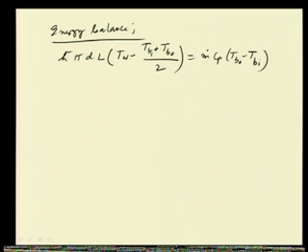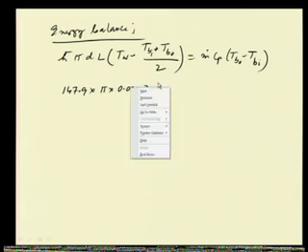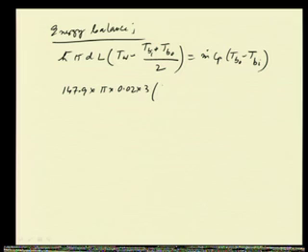So, this is that sensible heat that is being taken away by the fluid. m dot is the mass flow rate of the fluid. If we put these values here, we get 147.9 into pi into 0.02 into L, which is 3 meter, into (80 minus (50 plus T_bO)/2). T_bO is of importance to us, it is not known.